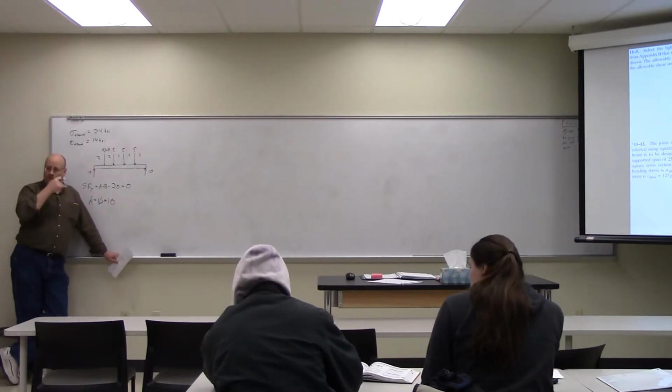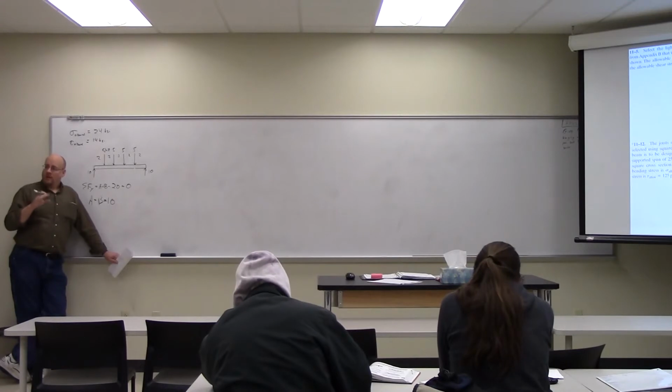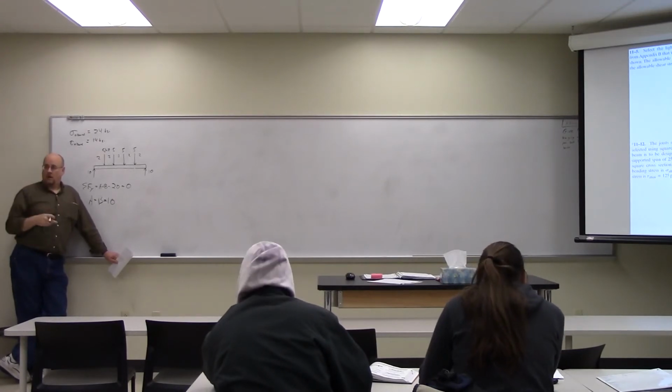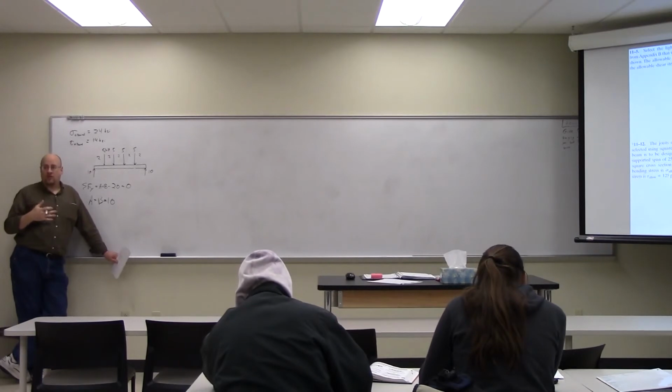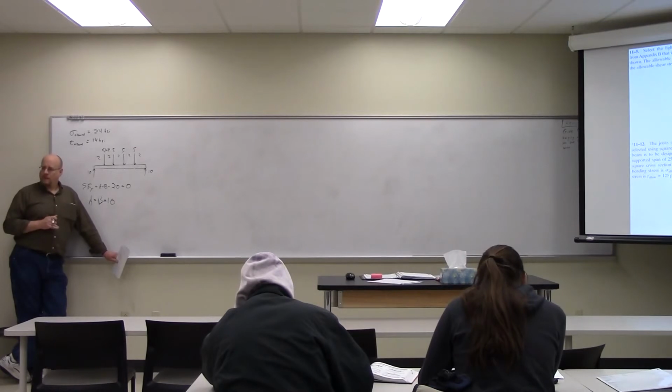Okay, I thought that makes sense. Earlier on in the course, didn't we say that things are more apt to fail in shear though? So things are weaker in the shear stresses. The shear stress for failure is typically lower than the normal stress for failure, as shown up here. Yes. Right? But that doesn't mean that the shear stress that's actually being applied is going to be greater than the normal stress that's going to be applied. So in the context of a beam, we're most often going to have a much greater normal stress than shear stress, due to the fact that it's designed to support moments. Because it's designed to support moments, exactly. Okay.